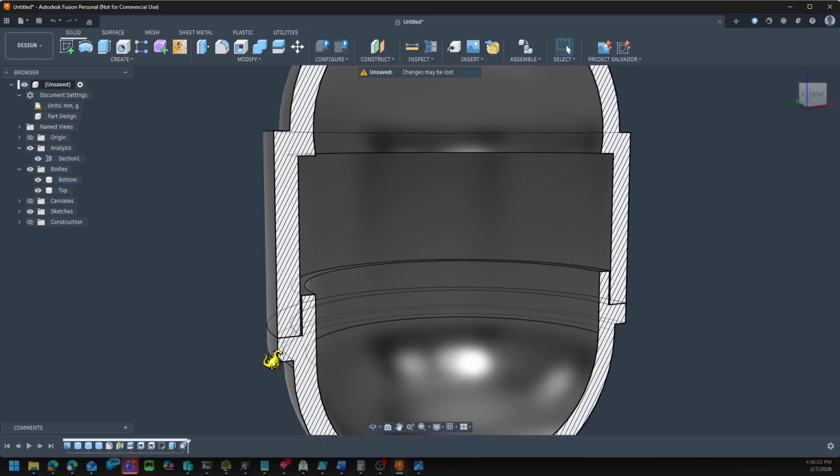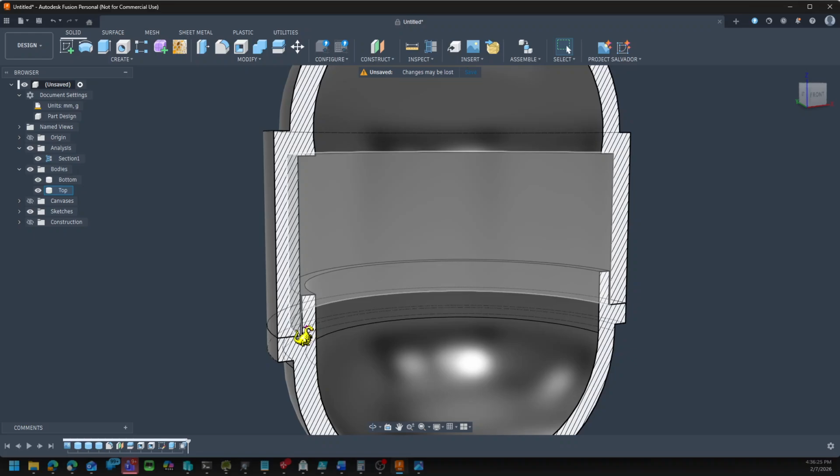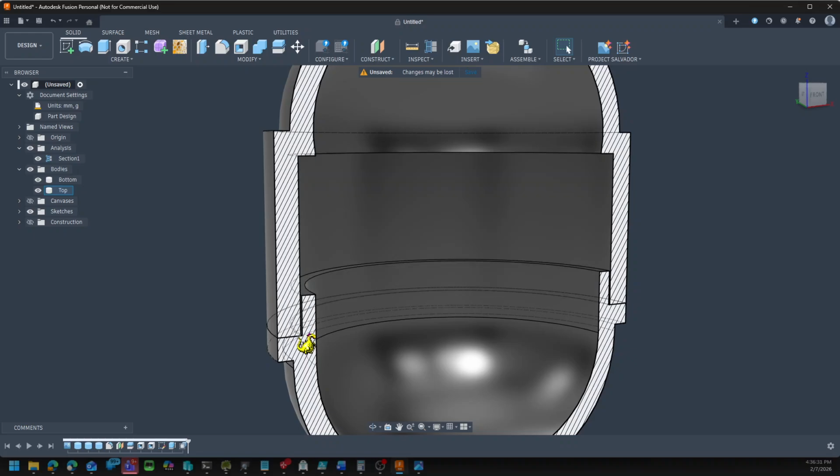The other way that I might do this, so right now that's just a press fit, and that would probably be fine for my printer. I know my printer can do that, but maybe your printer has different values for that. So the other thing that we could do, and this is what's on the Easter egg that I'm copying, is we can put a little snap fit in this. And to put the little snap fit in there, it's a little different. So I'm going to come back and take that tolerance out that I put in there. We'll get rid of that feature.